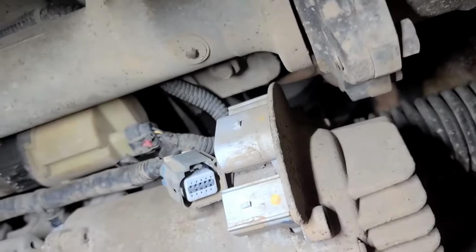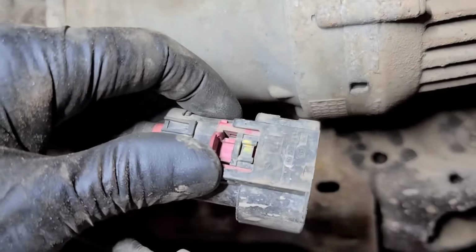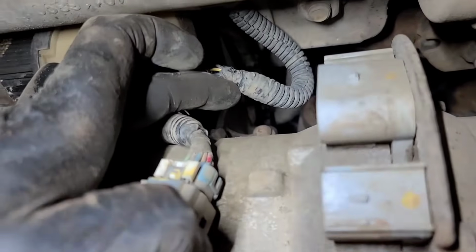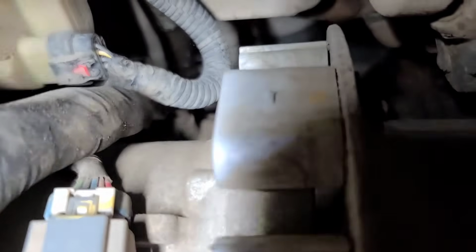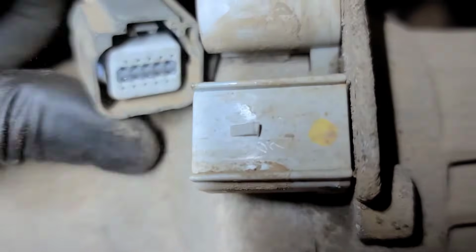To disconnect the electrical connectors from the steering gear, there are release clips, or secondary locks, on all of these. Slide them back. This one's got a ground wire up there. You see that little ground bolt way up there. So I'm going to focus on it right up there. Braided ground strap in here.